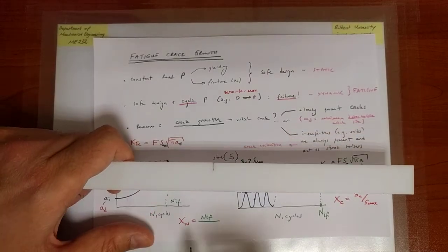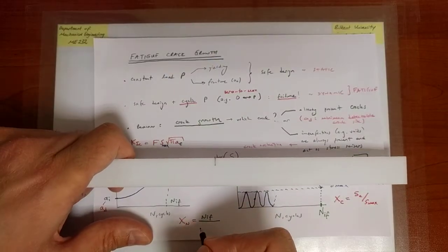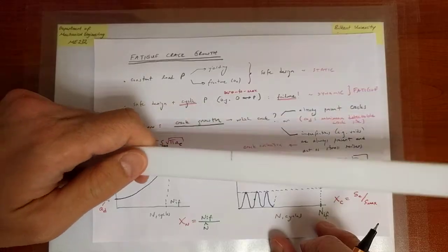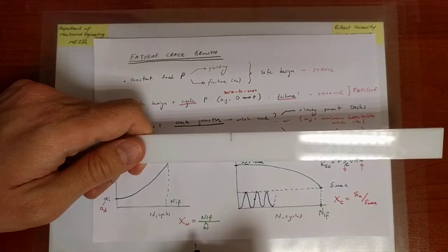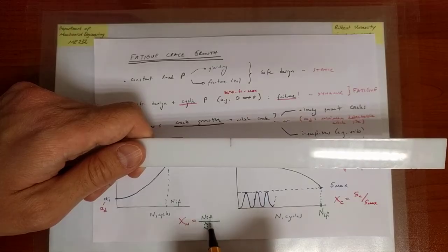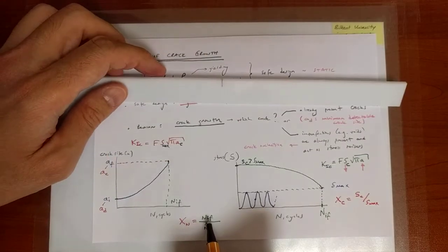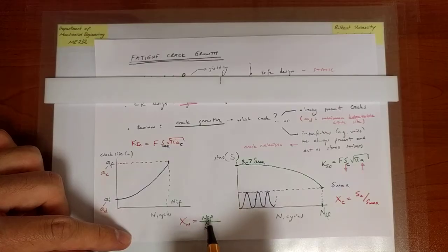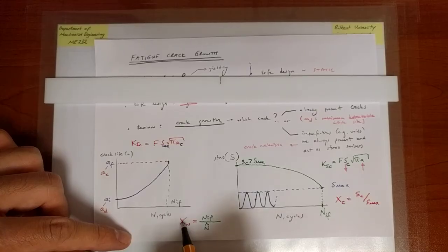And with that safety factor comes the concept of a service life. So what you're going to say is, okay, I know that I can cycle the structure through 1,000,000 cycles, but I want to do that with a safety factor of 10. So if I reach 100,000 cycles, I better stop, because with a safety factor of 10, I'm about to fail, right?